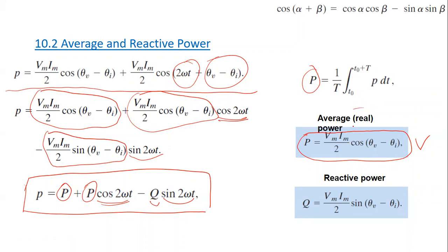The average power is called the real power because it is the power that can be converted to useful forms of energy, which could be mechanical energy, light, or heat. This is how we use electrical energy: as mechanical energy, for example in the washing machine; as light in lamps and TV; or as heat in the heater, the kettle, the iron.